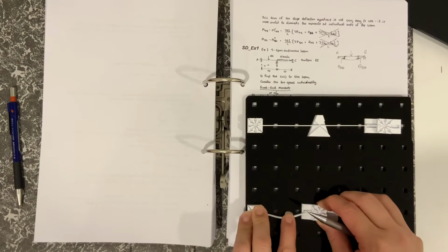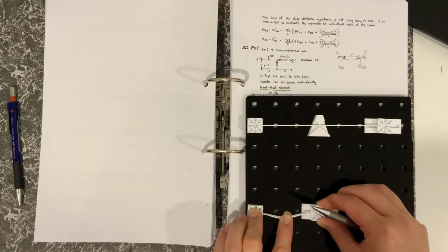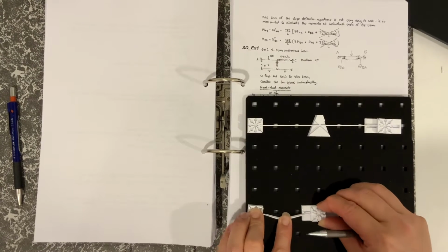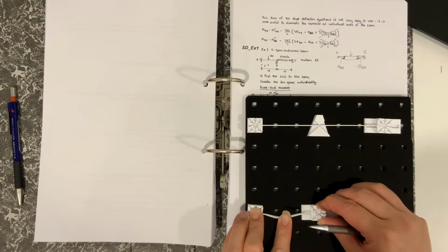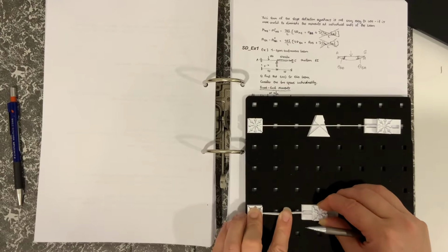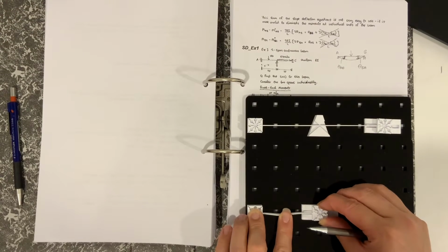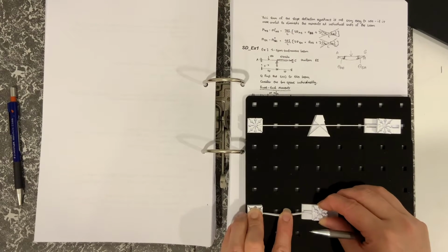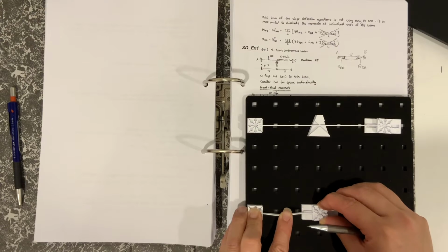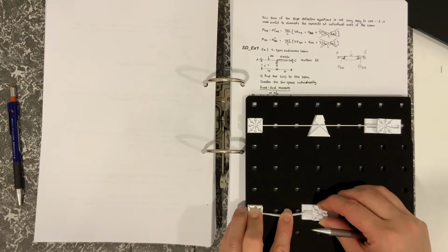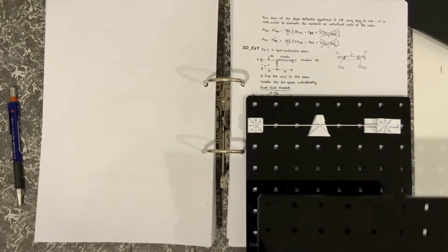We are able to look up that table and we can get the fixed end moment. I've put it down with my finger there, and you can see both sides have come out at 90 degrees, so there's been no rotation at A or B, and some moment has been generated.